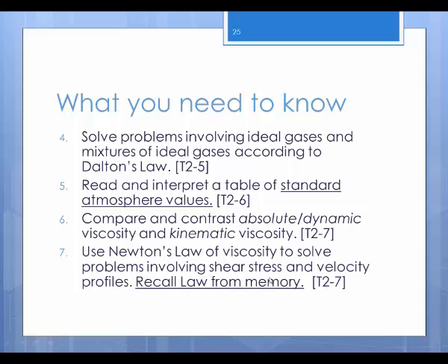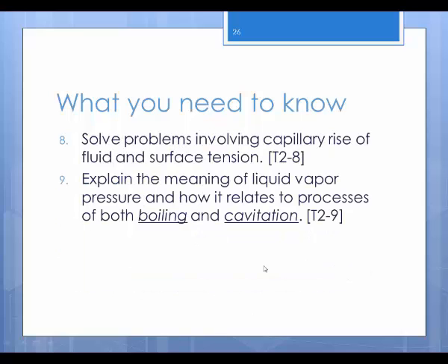Recall Newton's law of viscosity from memory and understand how absolute viscosity and velocity gradient actually create shear stress, and understand what makes a fluid Newtonian and non-Newtonian according to absolute viscosity and how it behaves when it's being sheared according to Newton's law of viscosity. You need to be able to solve these problems of capillary rise and understand exactly what surface tension is, at least so you can explain it a little bit, and know what liquid vapor pressure is, how to compare it, and how it relates to boiling and cavitation. There may be some other applications later, but those two are both really important for civil and environmental engineering applications.